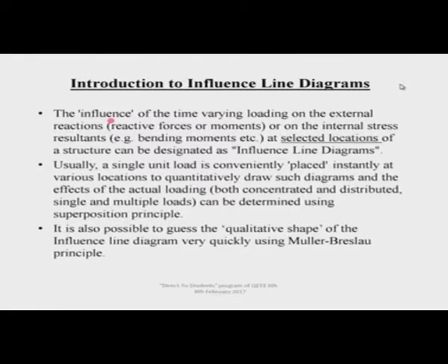The influence of the time varying loading on the external reactions, that is the reactive forces or moments, or on the internal stress resultants, that is the bending moments etc., at selected locations of a structure can be designated as an influence line diagram. Now, coming back to our discussion once again, usually we are exploring the effect of the loads at critical locations. So, that is how we define our influence line diagram.